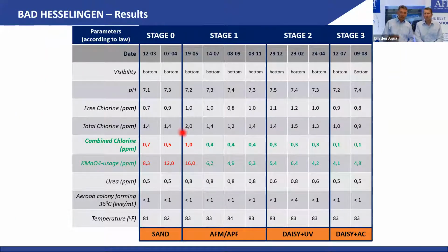This is if you backwash it, and this was the old AFM at 8 gallons, and this is then the result with the 20. So you see, if you do it the wrong way, your result is not great. It's terrible. But if you do it right, the result is great. And then with the combined chlorine, we dropped by 25%. Again, this was low pressure UV. Medium pressure probably would have dropped to 0.2. No real change in the oxidability in the KMnO4.